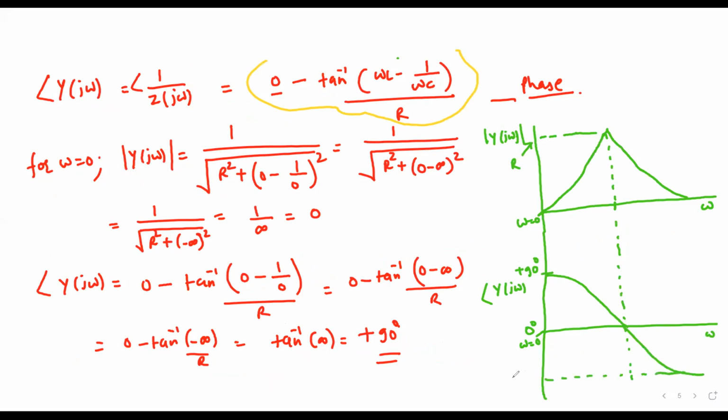So this spectrum looks exactly opposite to the impedance plot. So this is the function of a band pass filter. We see that this is the band pass filter response when we plot the admittance of the series RLC circuit. And if we plot the impedance of a series RLC circuit, impedance is the inverse of the admittance, or admittance is the inverse of the impedance. So they are opposite to each other.